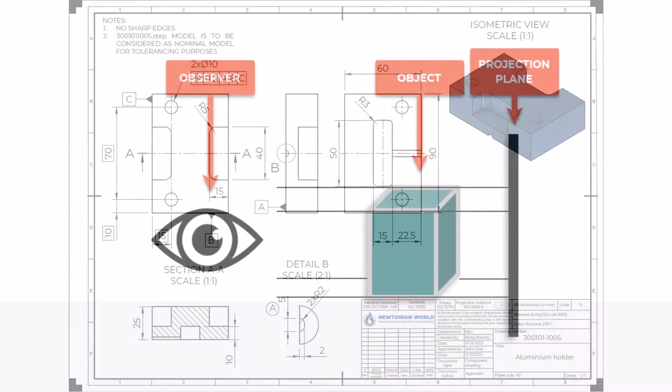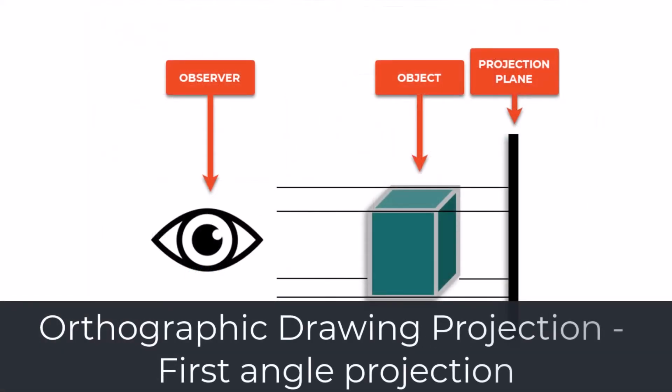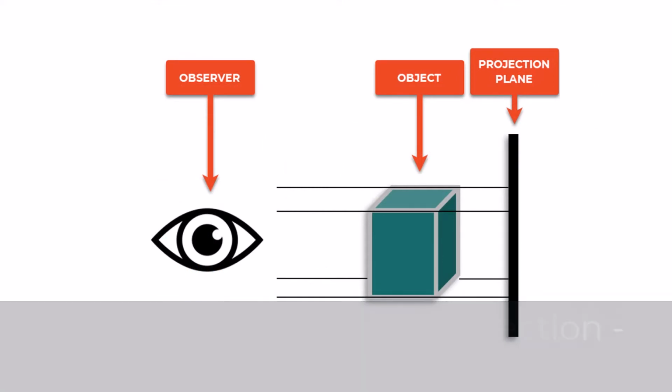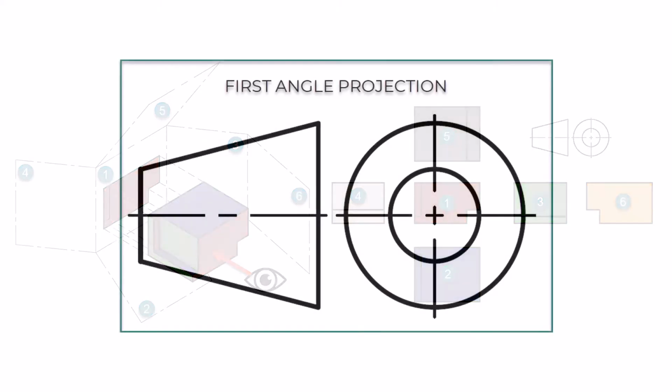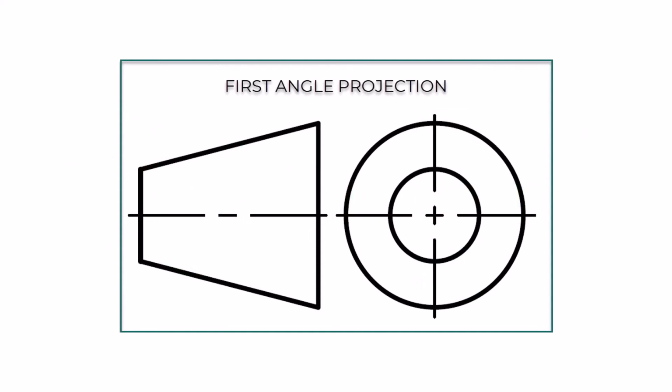5456-2-1996. First-angle projection. In the first-angle projection, the object is positioned between the observer and the projection plane. Every view is projected perpendicular through the object to the projection plane, i.e., the shape of the surface is parallel to the projection plane. Considering that we have 6 orthographical views, the projection planes of all views form a cube, and the inner faces bear the projected view. The first-angle projection is preferred in Europe. The symbol for the first-angle projection is defined according to ISO